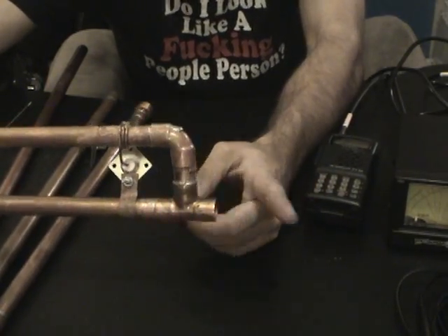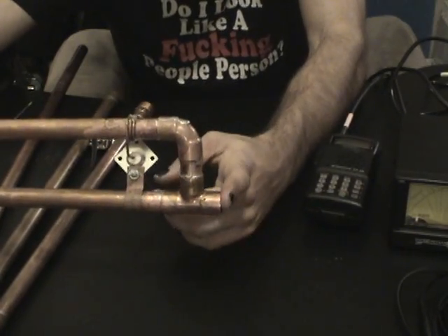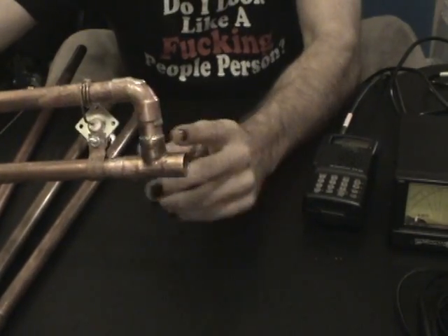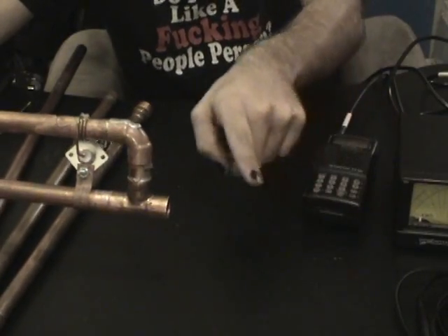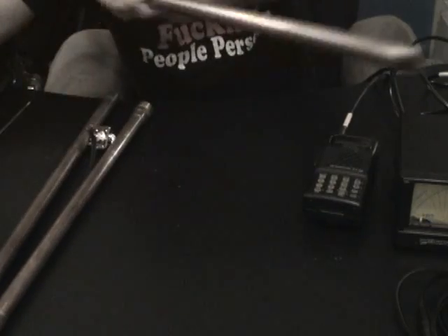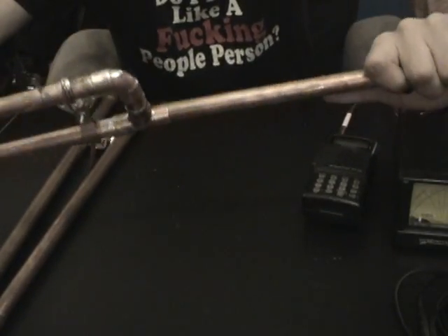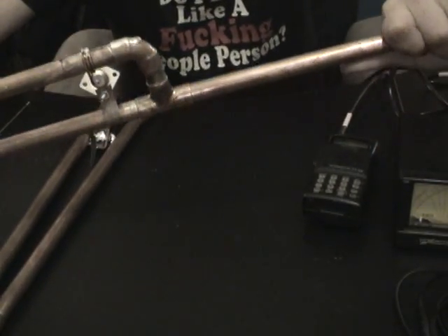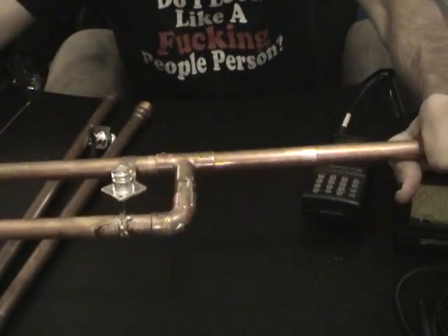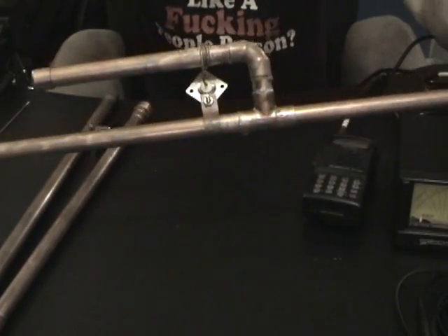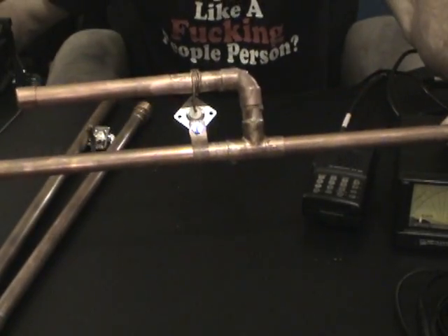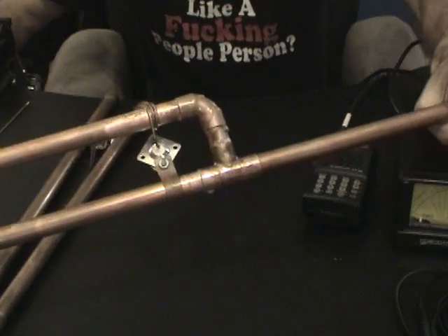Now I used the T connector, but this isn't 100% necessary. But, you know, the catch-22, I mean, you don't need to have any kind of length of antenna going in this general direction. This is just for mounting, so I pretty much have a spare piece of copper pipe. This will not affect the gain of the antenna whatsoever. That'll just fit in like so, and you can mount your J-pole antenna horizontally or vertically. Vertical is pretty much ideal.